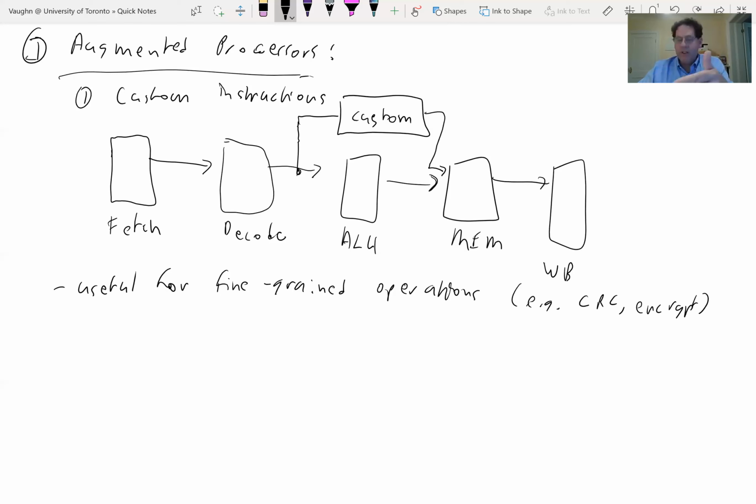Again, processors can do these operations, but they tend to involve a whole bunch of instructions. When you map them to logic gates and small block RAMs for things like encryption, you can reduce the instruction count a lot. So that's where custom instructions have had kind of their greatest success, with these kinds of instructions.